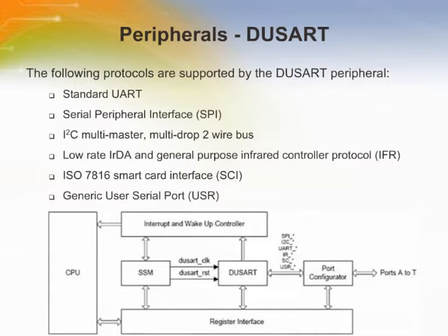The generic USART serial port is duplicated for each channel and shared between each protocol control engine using an array of multiplexers. This allows any of the protocols to be selected for either channel, allowing for maximum flexibility. Note that each serial protocol may only be used once. The same protocol cannot be used simultaneously on both channels.